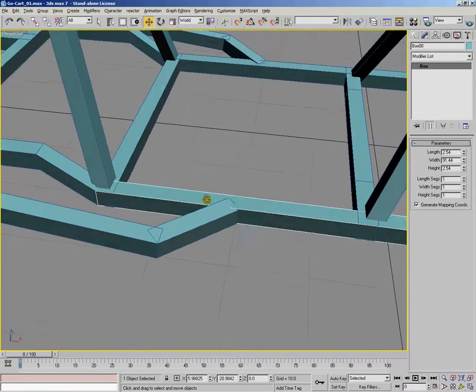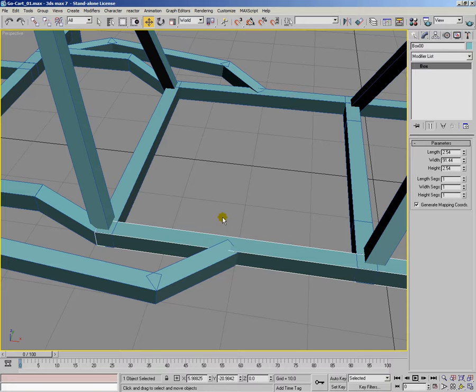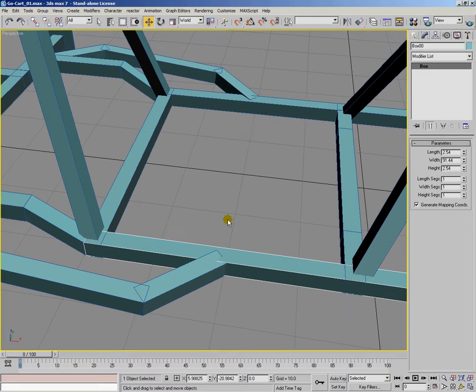Now, this was actually on an American website, so all the measurements are in imperial. For instance, I'm British, and in the UK these days we use metric. And most computer software actually works in a metric system as well. For instance, all of these units are based on units of 10, so it's a metricized system. So what I've done is I've worked out the difference between an inch and a centimeter, and basically for every inch you get 2.54 centimeters, and I'm using that as the basis of this model. So in other words, one unit in our model is equal to 1 centimeter, so that means that every inch is equal to 2.54 units.